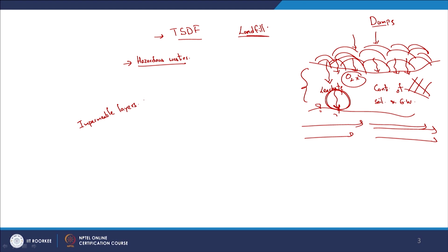So there are different kinds of impermeable layers now. Let's say bentonite clay, with optimum compaction anyway, has a hydraulic conductivity that is very low, right? Again, that's one aspect, but even then, depending upon alternate cycles of drying and again being in contact with moisture, it can develop cracks and so on. Again, it depends upon the scenario or the site. So that's not the only option that we look at.